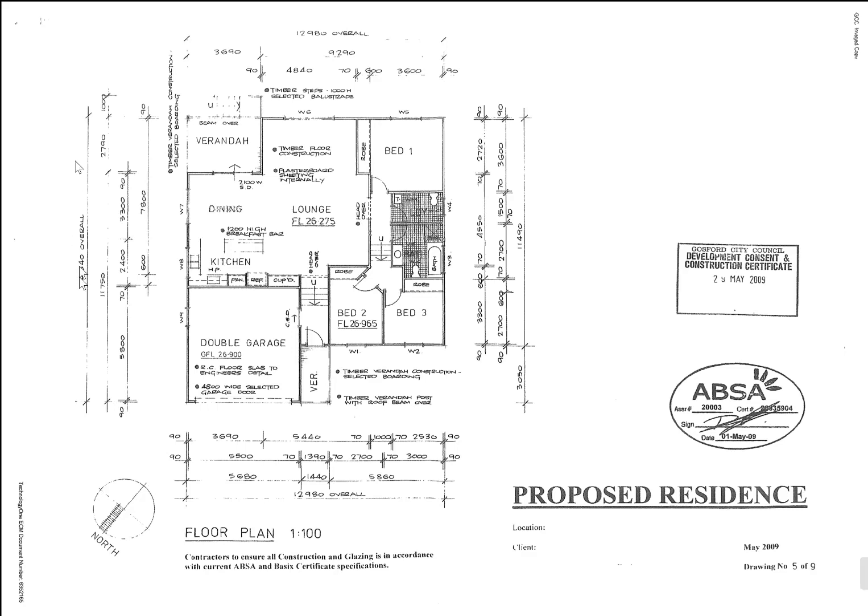What happens then is as we move closer to the actual building, we start picking off the dimensions for external rebates in the wall. We've got a veranda there on that end, and down here we have another rebate, so we get the dimension of the length of the veranda there. We'll have the same sort of thing with the width. We've got the overall width, and we start picking off that rebate, the width of the rebate, the width of the veranda. The same thing at the back there. The 9220 comes away from the 12980 and gives us the 3690. Then we move closer in again and we start looking at the internal walls, the distances, so we can actually set out all our internal walls.